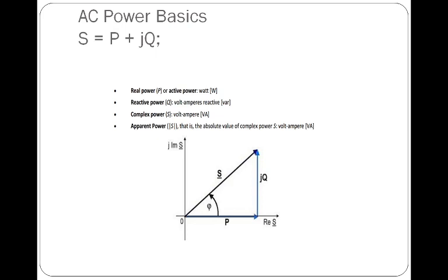If a capacitor and inductor are placed in parallel, then the current flowing through the inductor and the capacitor tend to cancel out rather than adding. Conventionally, capacitors are considered to generate reactive power and inductors to consume it. This is the fundamental principle for controlling the power factor in an electric power transmission system. Capacitors or inductors are inserted in a circuit to partially cancel out reactive power consumed by the load.